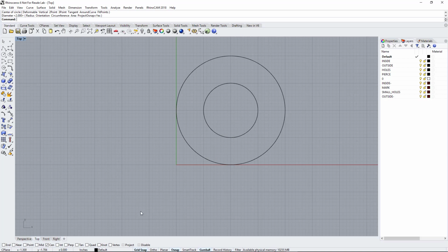If I wanted to, let's say, put a crosshair in the middle of that, I can turn on the quad snap and grab a line. Now it's going to snap there, there, there, there. 4 places. And I can go ahead and put a crosshair in there. Intersection snap would snap to any point where you have intersecting lines.